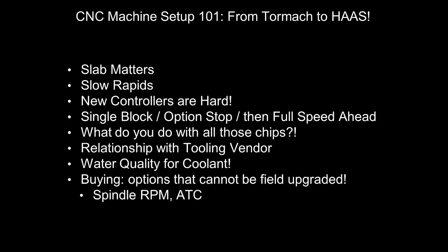Water quality. Fun fact, this actually matters a ton. The city water in Zanesville, Ohio, where I'm living, happens to be super hard, and Haas actually has a really good YouTube video on how to deal with coolant in your machine. But long story short, as your water evaporates, the minerals that make water hard stay behind, so your water in your machine will get harder over time, which will cause bad things to happen to very expensive machines that I'd like to stay nice and pretty. So I just finished today setting up our reverse osmosis system, which ended up being much more of an undertaking than I had planned. But getting good water quality into a machine that should last for years is really important. And nobody tells you that when you're buying your first VMC.